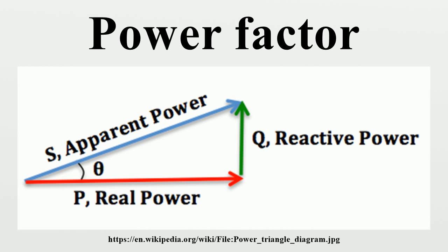The reactive elements can create voltage fluctuations and harmonic noise when switched on or off. In the worst case, reactive elements can interact with the system and with each other to create resonant conditions, resulting in system instability and severe overvoltage fluctuations. As such, reactive elements cannot simply be applied without engineering analysis.